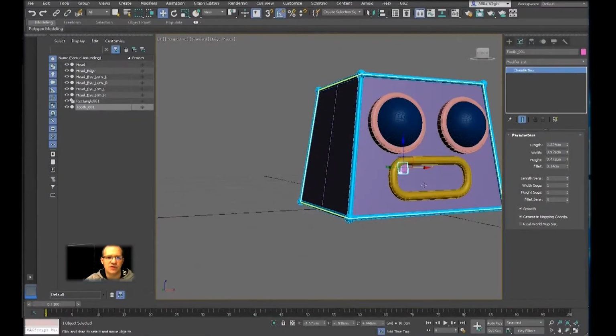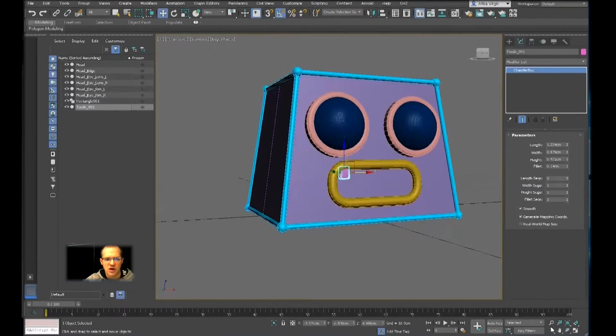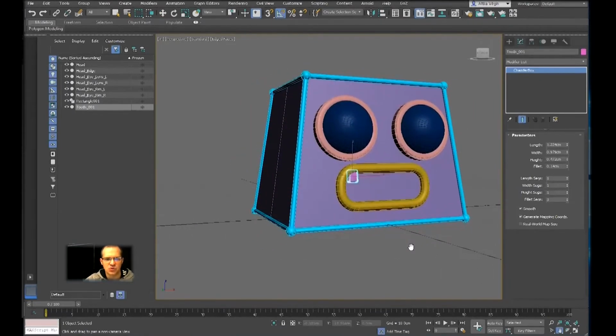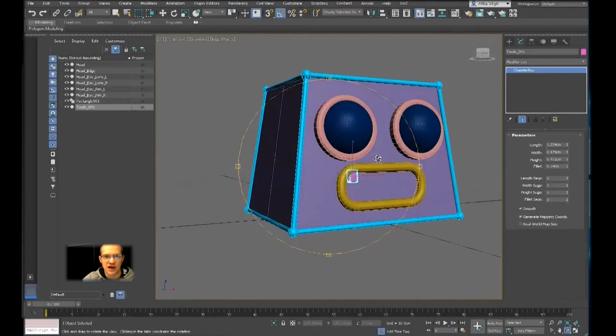Anytime, if you have no mouse or you are in travel or something, you can use these. The zoom, this is the first one. It's the basic zoom tool. We have a pan, the hand tool, and this is the orbit. There is even a hotkey for the orbit. It's Control R. Okay, we are not using this too. It's quite a rare thing. But if you want to rotate around your element and you don't have a mouse, you can quickly press Control R. Now you can rotate around with the touchpad and press Escape to leave this kind of rotation mode. It's not that fast, but at least it's working.